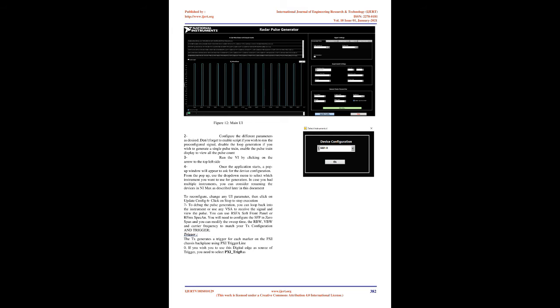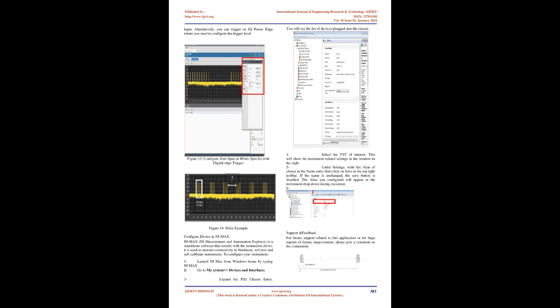The binary code consists of a sequence of either +1 and -1. The phase of the transmitted signal alternates between 0 and 180 degrees in accordance with the sequence of elements in the phase code, as shown on the figure. Since the transmitted frequency is usually not a multiple of the reciprocal of the subpulse width, the coded signal is generally discontinuous at the phase reversal points. The selection of the so-called random 0, π phases is in fact critical.